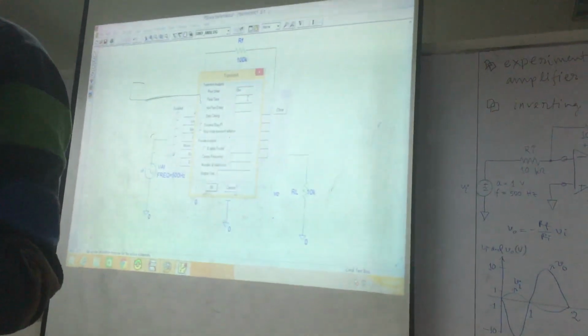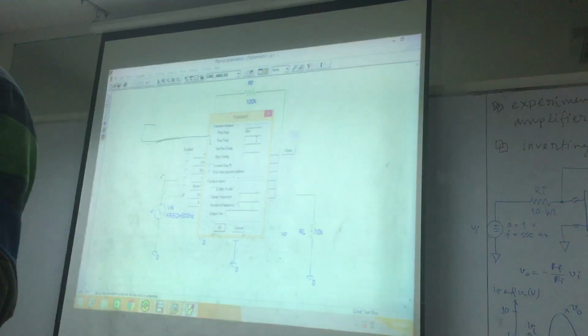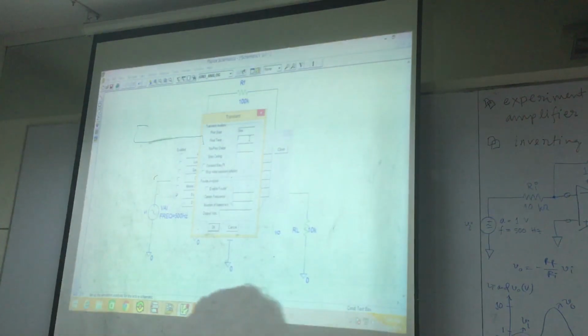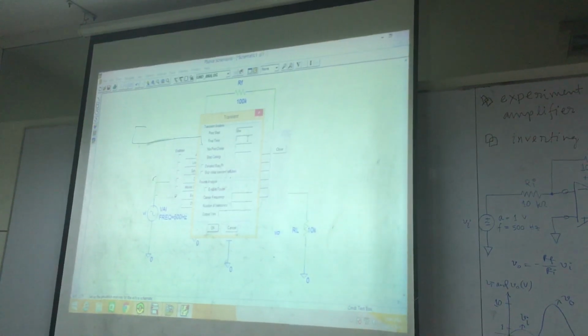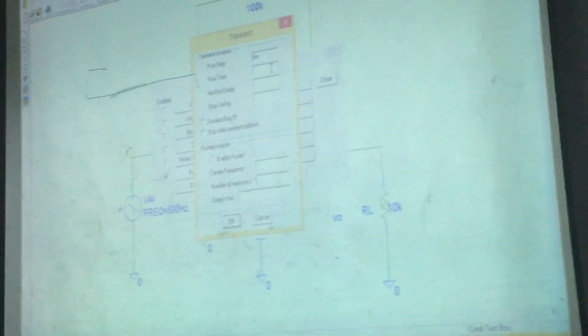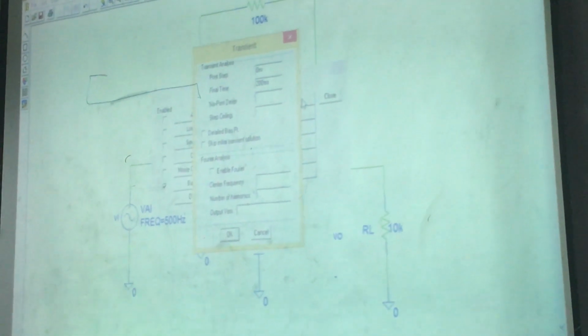But the usual rule of thumb is to have as much data as possible, not just a few cycles. So we're going to take basically the first 100 cycles. You may not understand it here, but you may in some later courses: taking just the first few cycles is not enough. Sometimes you may need the first 1,000 cycles even. Right now we're going to take just the first 100 cycles. How many milliseconds? 100 cycles, each 2 milli, so 200 milli. No print delay is needed.